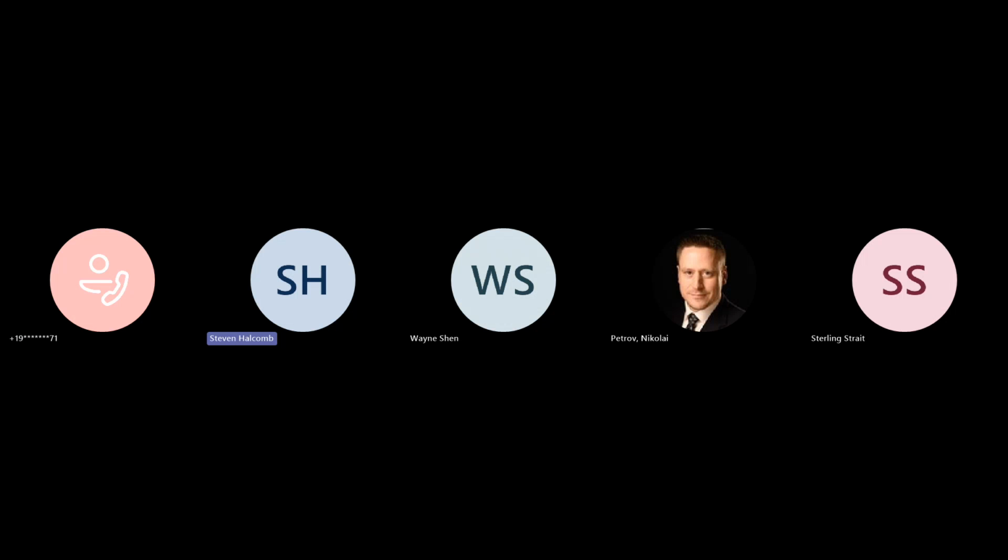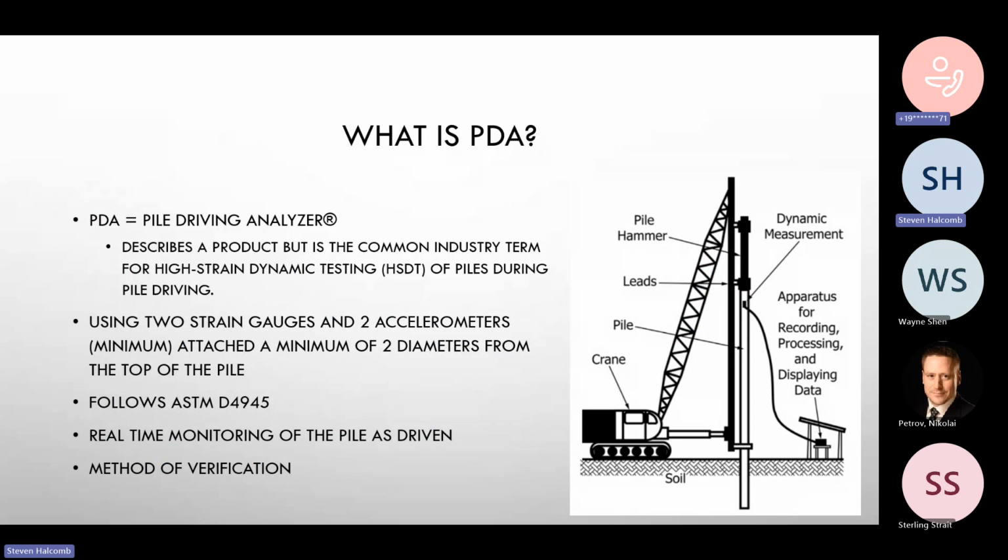But there is ASTM D4945, which gives all the ins and outs if you want to get into some of the details of it. But a simple definition, if you will, or approach, classification is real-time monitoring of the pile as it's driven.